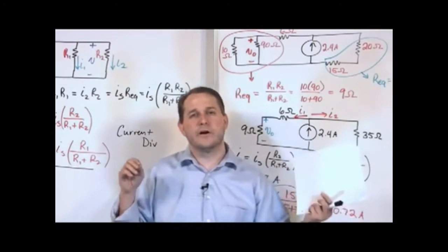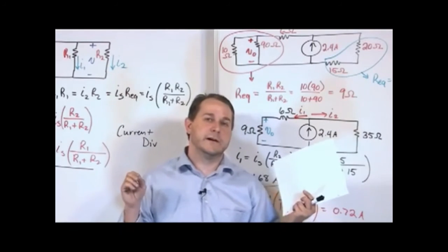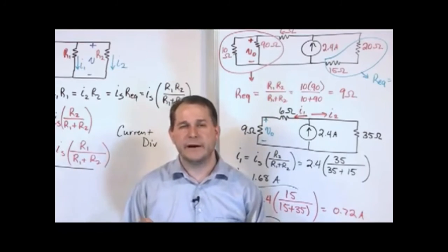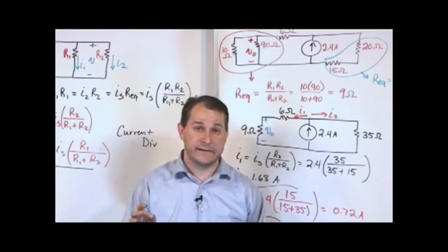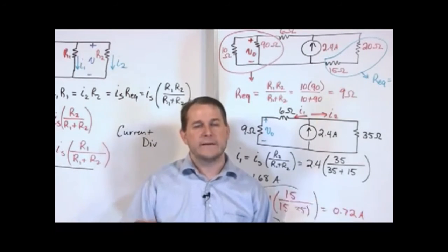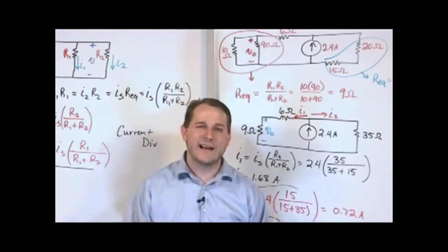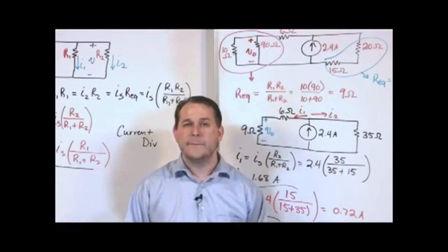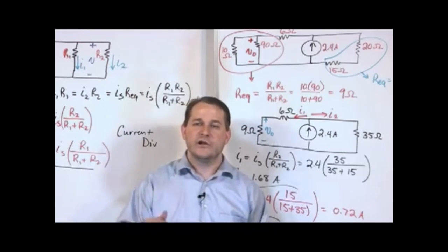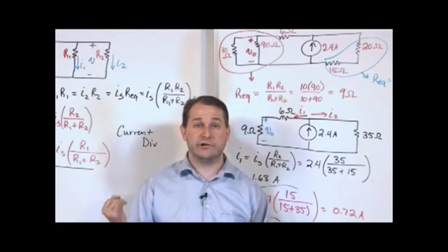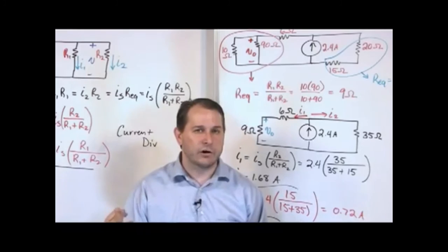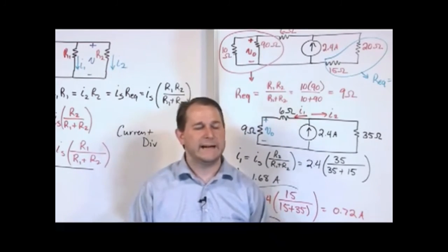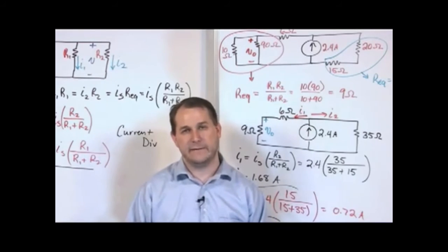We've learned about Kirchhoff's laws, Kirchhoff's current law and voltage law, we've learned about power, and honestly if I had to pick one of the most important things that I've tried to get across in this course, it is the sign conventions. The sign conventions can fail you faster than anything, because if you don't understand them, you'll never be able to write a power equation correctly. You'll never be able to write a Kirchhoff current law equation correctly, and you'll never be able to write a voltage law equation correctly. And if you can't write those, you can't solve anything, right?